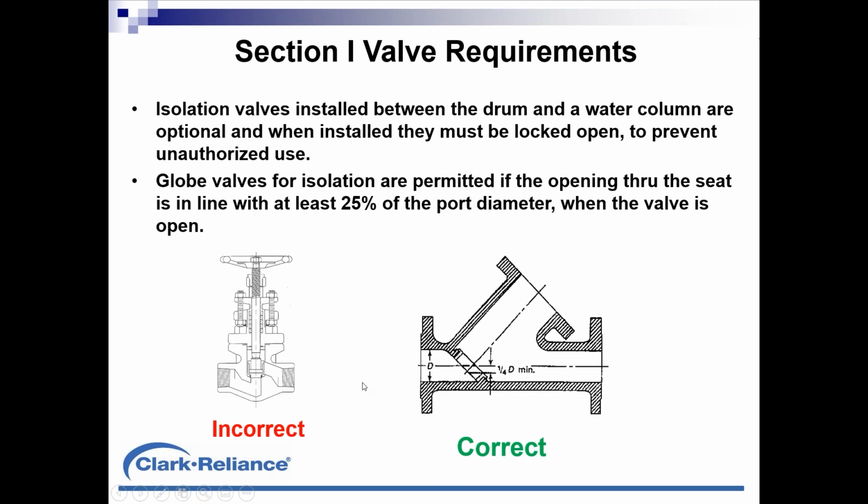And there's no way to rod this valve. Due to petitioning of the ASME code, going back to about 2006, it became part of the code in PG-60: the rules for the use of globe valves in the 2007 edition of the code. A globe valve is permissible if 1/4 of the inlet port diameter is above the seat when the valve is open.